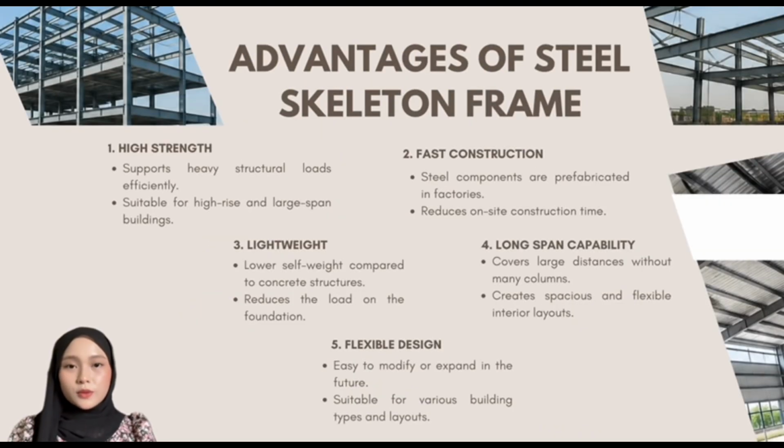Okay, now I will explain the advantages of a steel skeletal frame. First, an advantage of a steel skeletal frame is high strength. Steel has an excellent strength-to-weight ratio, which means it can support very heavy loads without requiring large structural members. This makes it suitable for high-rise buildings, commercial buildings, and industrial structures where strong structural support is essential.